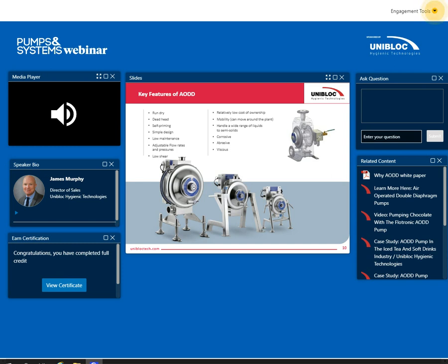And something else that's nice about it is since it's not electric, we don't have to use a VFD, a variable frequency drive. We just adjust the flow rate and the pressure by the air. So depending on the air inlet and the size and the amount of pressure we have, we can just use a ball valve to adjust that as well. And then as we pointed out earlier, the fact that they're low shear and they don't damage product also makes them a real nice advantage.